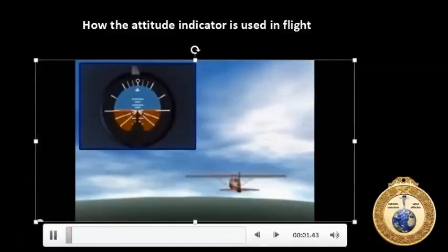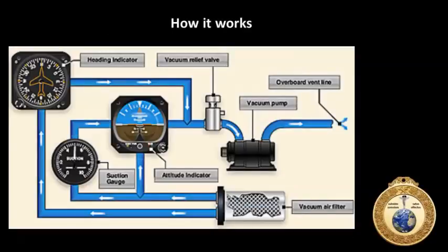Okay, so I thought that was pretty cool. A pretty cool video. It's trying to start up again on me. Now, back to our heading indicator. Same thing. Air sucked through the instrument case, through a relief valve, through a vacuum pump, and overboard vent line.